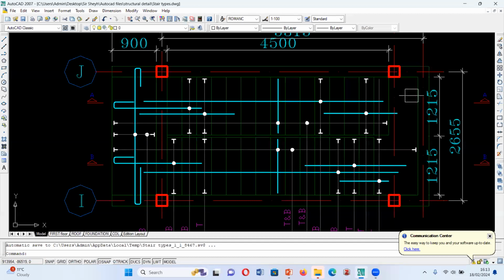at the first floor, and this is where the stair is coming from the ground floor. So if we have something like this, and we have this landing here, what it means is that this bar coming like this is going to connect this support together with this support, and it's going to be our main bar for this flight.